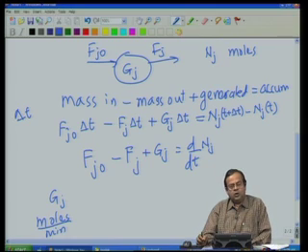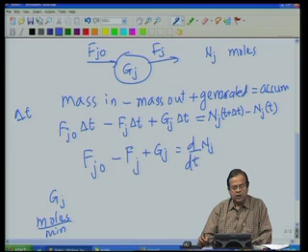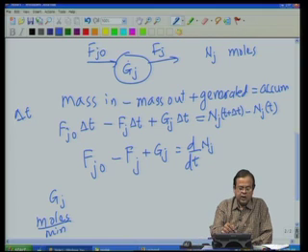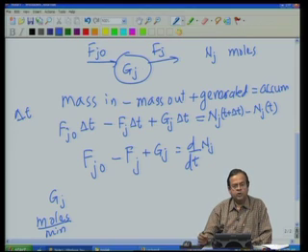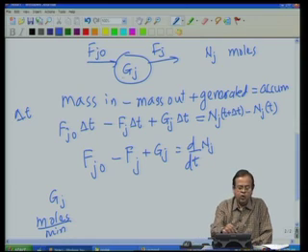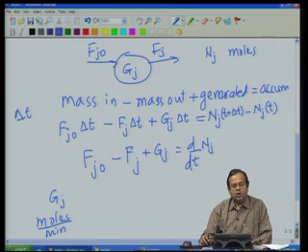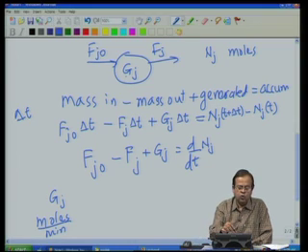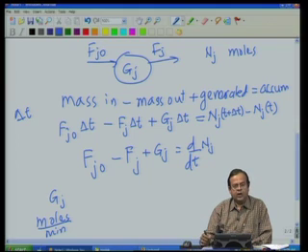If, for example, we assume that the working conditions are such that there is no variation inside the reactor, variation of temperature or concentration or any quantity that influences the rate of reaction, that is, temperature is uniform all throughout, concentrations are uniform all throughout, and you would have by now guessed we are talking of a perfectly mixed reactor, a reactor in which there is very good stirring, so that there is no variation within the reactor.